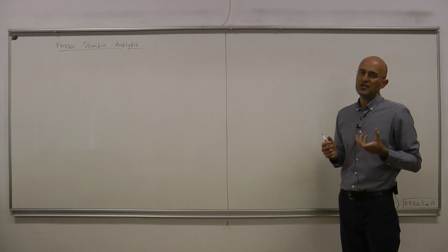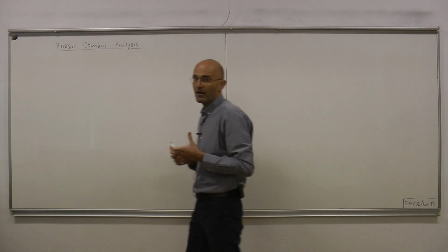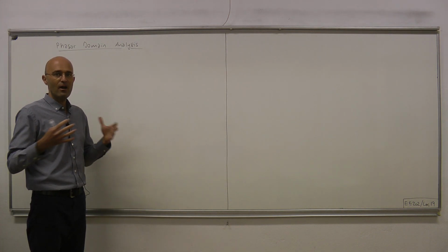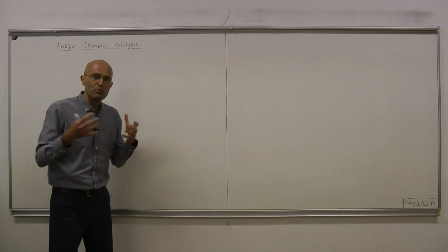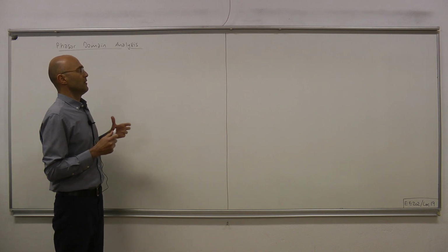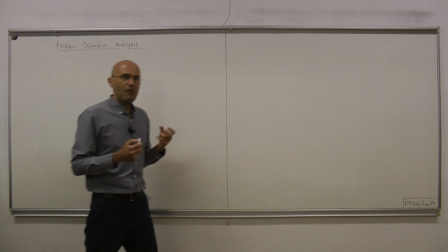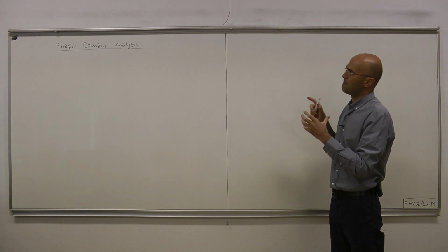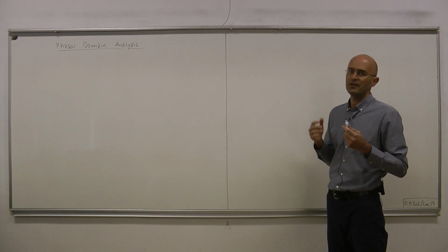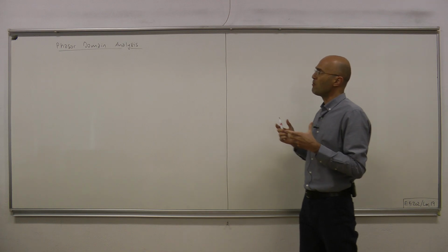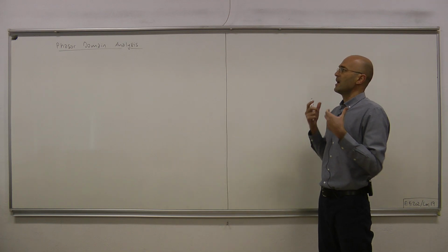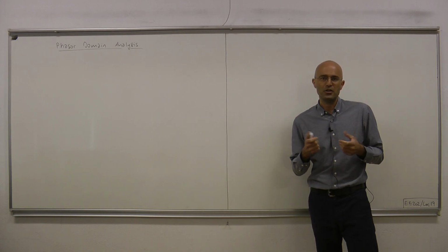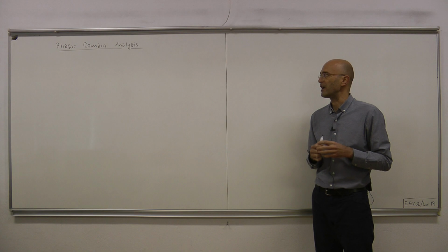Now, since phasors satisfy KCL and KVL, plus the terminal equations, they all boil down to a sort of Ohm's law. Combining those two facts motivates us to look at circuits in sinusoidal steady state from the phasor point of view. And that's the motivation for our phasor domain analysis, which we start developing in this lecture.